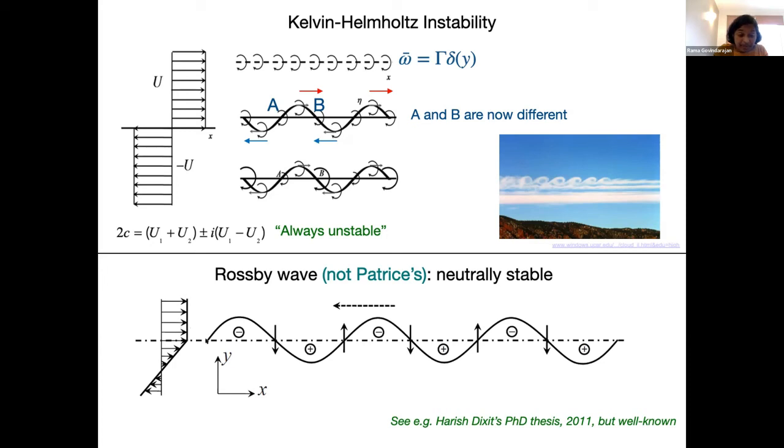So if you perturb the interface, this dashed line, if I make it like this, then what will happen is here the vorticity is 0 and here the vorticity is a number. So relative to the surroundings, this one will have negative vorticity, and that one positive vorticity. Any positive vorticity introduces a downward flow here and upward flow there. Negative vorticity, downward flow here and upward flow there. So you'll be inducing these downward and upward flows, which will pull this interface down in these parts. That's all that is going to happen. In other words, there's a wave propagating in this direction. These particles may be going up and down, but the minima and maxima of these waves will be propagating in that direction. So you just have a neutrally stable wave.